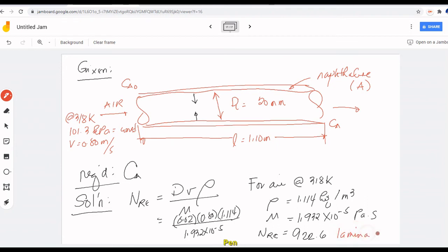If the flow is laminar, there's a need for us to use the figure for laminar flow, the one that I have discussed to you a while ago. In that particular figure, aside from the Reynolds number, you will be needing the Schmidt number for the abscissa.